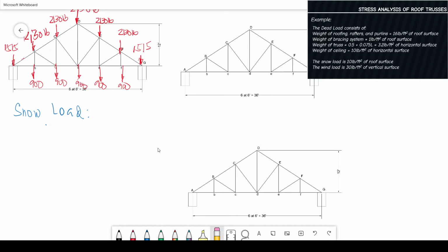So for snow load, we have the panel load for the top chord. Again, we do not put it on the bottom chord, since the weight is captured by the snow load on the roof, unless the load is carried by the ceiling. Probably the snow load does not go to the bottom chord, but I bet you don't want that to happen.